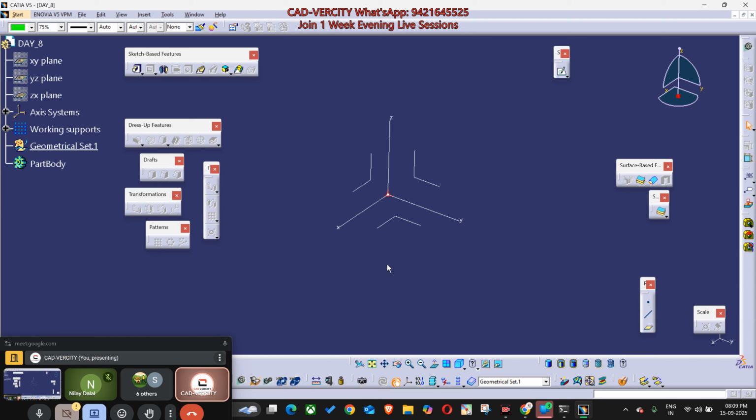For the surfacing, we will use GSD, but after surfacing, we will have to start the part design, because we can't deliver only a surface to any tool maker. Each surface should have some thickness, and for thickness we use part design. There will also be fixation features like screw bosses, where we use screws to fix that part on any structure.